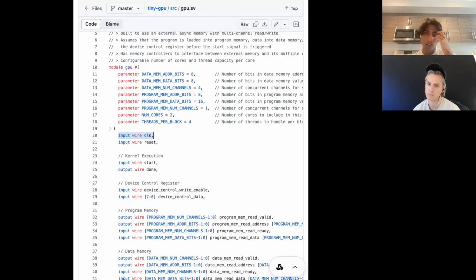And the other thing that's important about the clock is you can't just set the clock insanely fast because the chip actually has physical constraints, right? If you need something all the way on the left side of the chip to communicate something all the way on the right side of the chip in one clock cycle, there's actually constraints there because the electricity takes time to propagate across the chip, which means that your clock cycle needs to be longer than the maximum propagation time of signals that need to communicate in your chip. And that's actually something that the EDA stack does. So that's one thing. It's like static timing analysis. Make sure that all the timings in your chip are valid based on the clock cycle time.